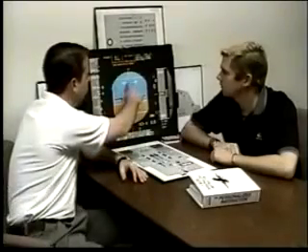In normal law, describe to me some pitch limitations. For example, pitch up and pitch down. Okay, as opposed to pitch left or pitch right? Exactly. Okay. Maximum pitch we can get on this aircraft in normal law is 30 degrees. As we get to 30 degrees, energy is going to deplete, and then it'll be limited to 25 degrees. That's true for all configurations except for flaps full. In flaps full, we're limited to 25, and as energy depletes, it'll decrease to 20 degrees. Nose down, regardless of the configuration, the maximum is 15 degrees. Okay. And what indications will you see that you have that protection? You'll see green tick marks at 30 and green tick marks at 15, just like these green tick marks.